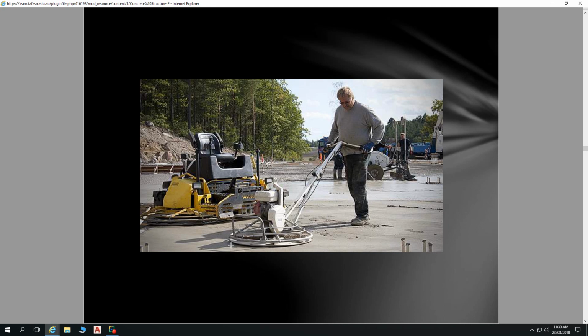Yeah, and there's several ways of doing that as well. So with a stiff bristle broom, you get those lines. And I think if you look at the concrete as you head out from here, there are things like that happening in the concrete outside there. Oh, actually, that one out there, the footpaths at the car park, they've been blasted away. So you get water to wash away all the fines from the top of your slab to expose that aggregate, give you more grip. So that's another way of doing it.